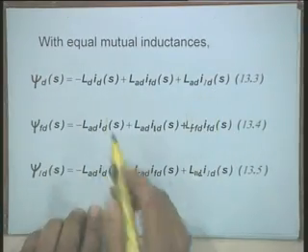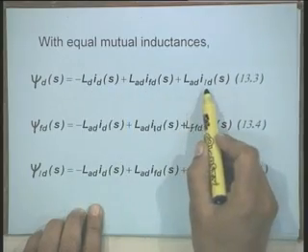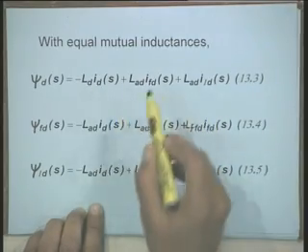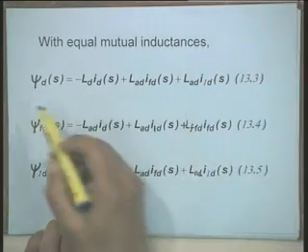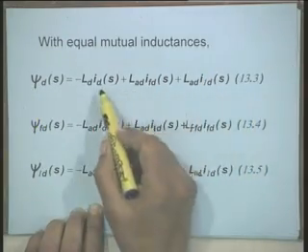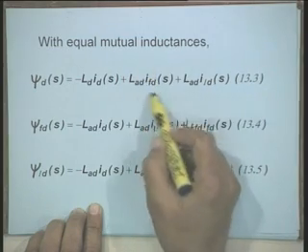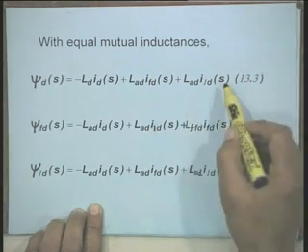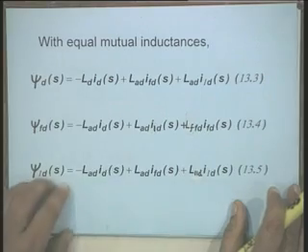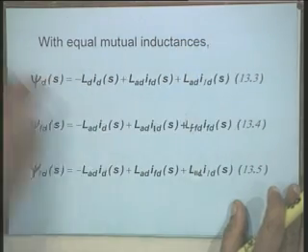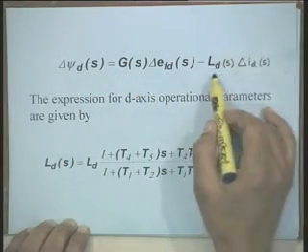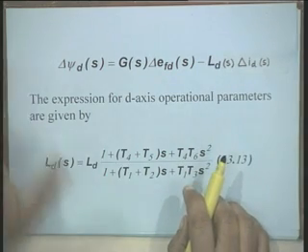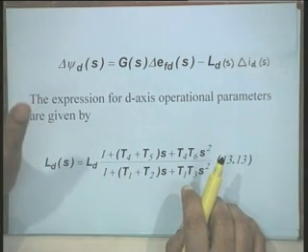In this equation we have ID, IFD and I1D. What we have now done is that these will be expressed in incremental form. Then in this expression you replace delta IFDS and delta I1DS using those expressions. Once you do, you will find that you can write the expression for delta psi ds as GS delta EFDS minus LDS delta IDS. Do you appreciate these steps?